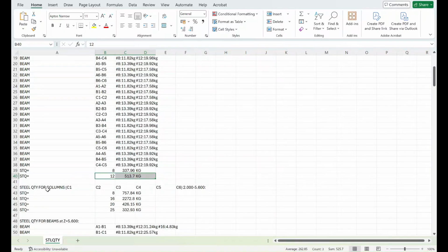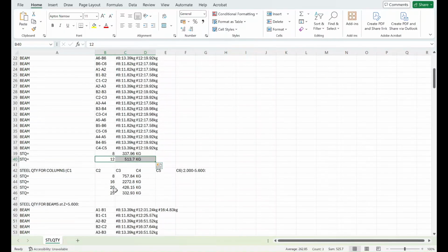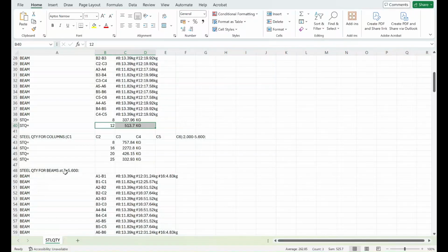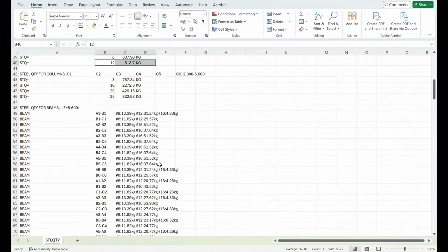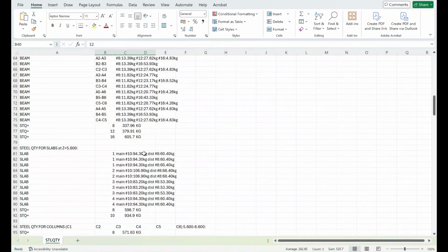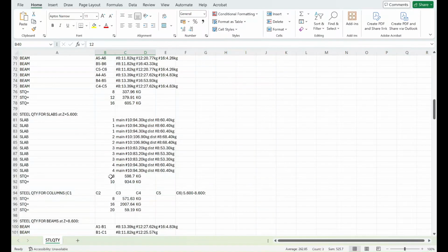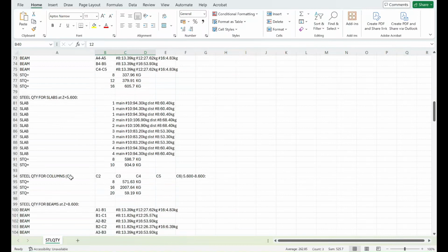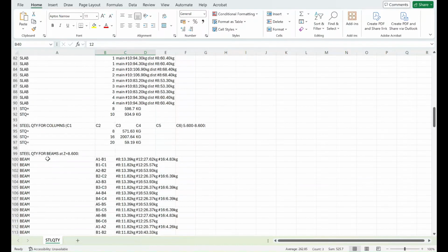In the fourth row you see column rods for the grouping of C1, C2, C3, C4, C5, C6 columns from foundation bottom to ground level, including L-bend at bottom. The 8 mm indicates lateral ties requirement. 16, 20, 25 mm indicates main rods of columns up to ground level.